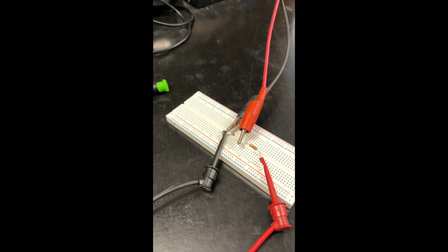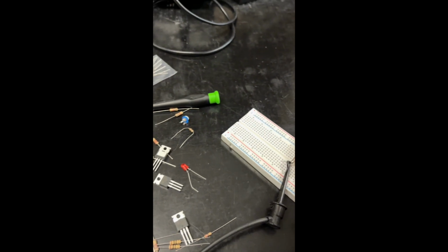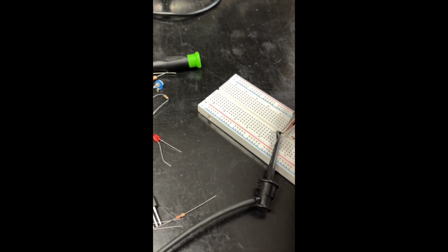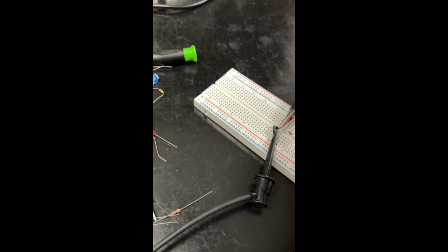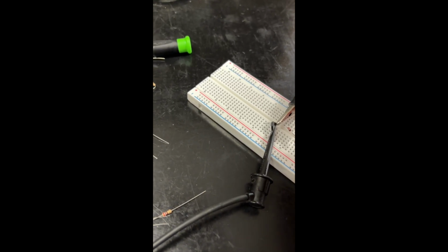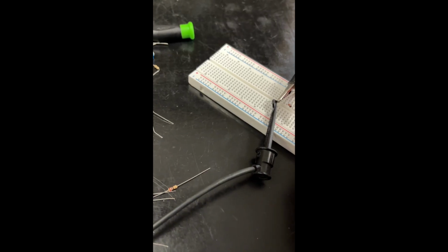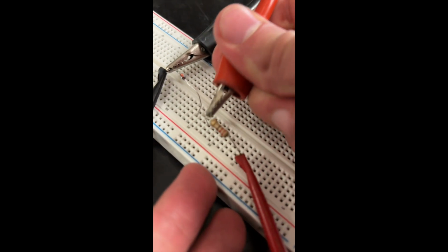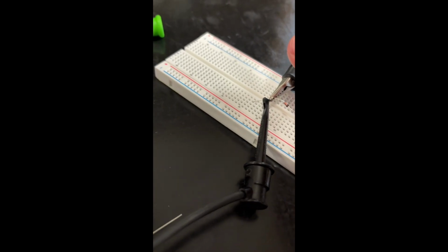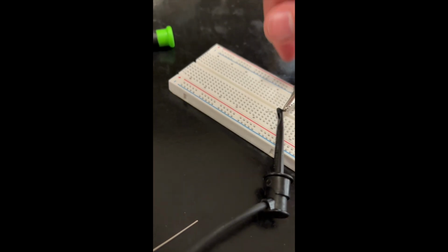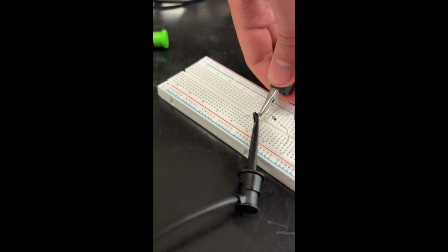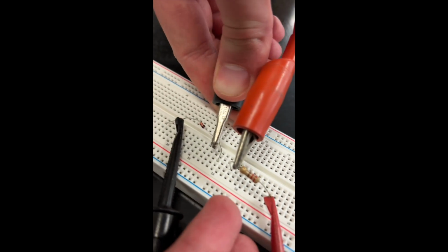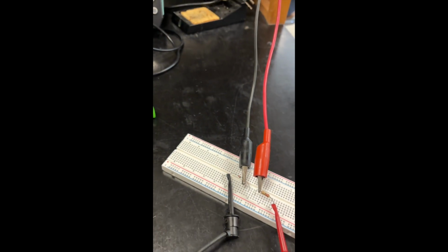And now I'm just going to set this up real quick to take current with that off. And for exercise E, the measured current at 0% on the potentiometer, full bright. I am using 220 ohm resistance because I calculated the safe value for 25 milliamps to be 212, which is right there.